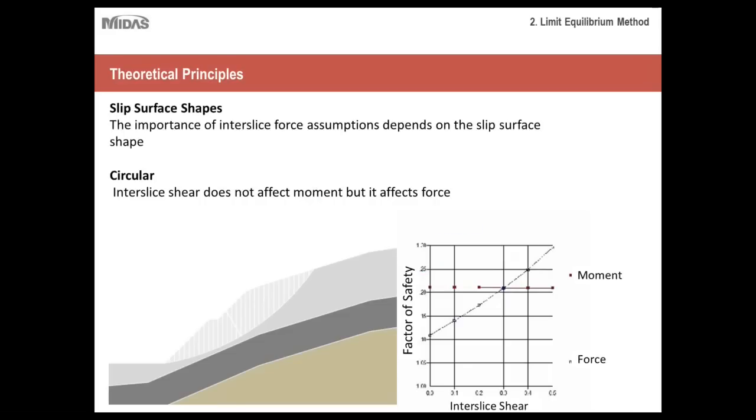Okay, so now let's go over just how to decide upon your slip surface shape. With most programs that are out there, they'll allow you to select or to create your own arc failure shape. So here's just a sample of a circular arc failure shape.